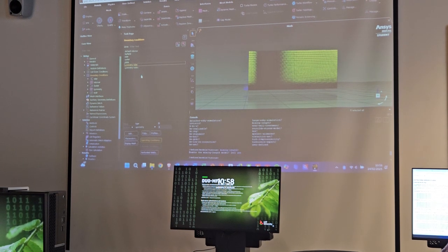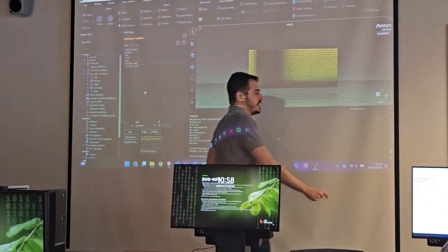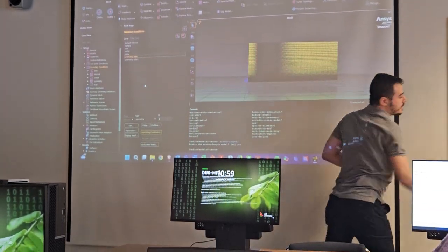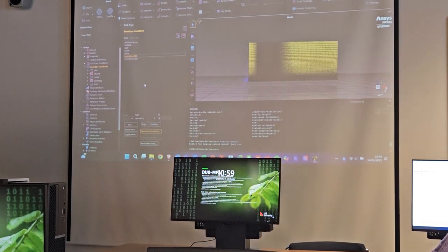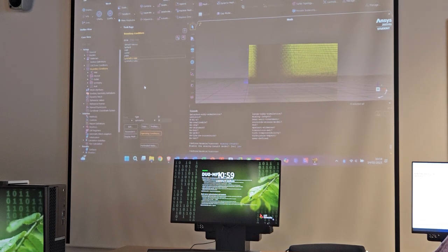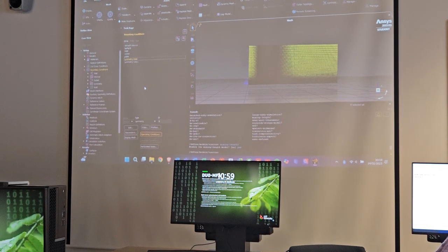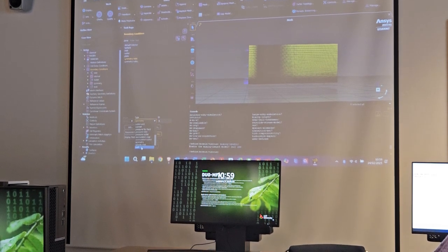Then we have symmetry at the inlet. So the first part over here, before the plate on the bottom. For other turbulence models, setting it like a symmetry is fine. For this mixing length, apparently no. It messes things up with the inlet boundary conditions, so we set it like a slip wall. So we do that by changing the type, from symmetry, we go to wall.